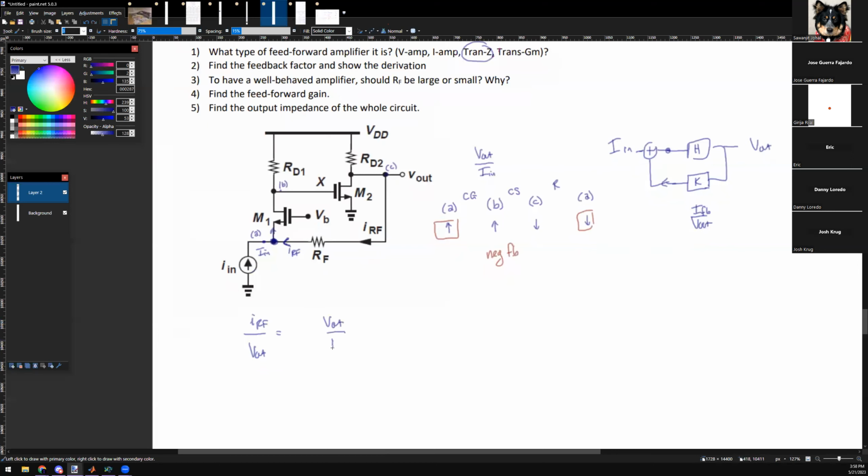Yeah, I think you're right. I find this and I invert it, right? I find the resistance looking into this path, and I think this bottom guy, V out over IRF, is going to be the impedance into this path, but I break the connection, right? I have to open this guy. K exists in an open loop scenario. So I open up the loop, I break this guy open, and I find this guy. So I think the answer is RF plus.